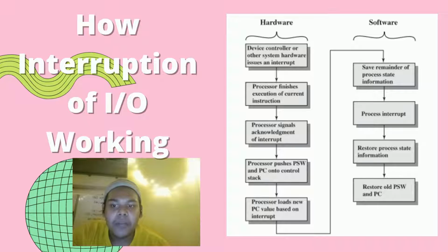There may be a single program, or one program for each type of interrupt. This information may have been included in the original interrupt signal, or the processor may have to issue a request to the device that issued the interrupt to get a response that contains the needed information.